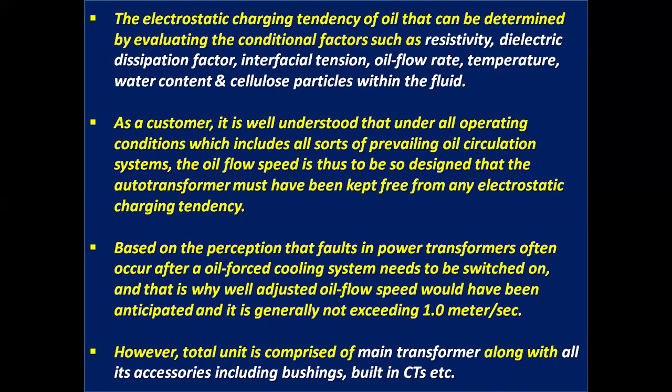As a customer, it is well understood that under all operating conditions, which include all sorts of prevailing oil circulation systems, the oil flow speed is to be designed so that the autotransformer is kept free from any electrostatic charging tendency.